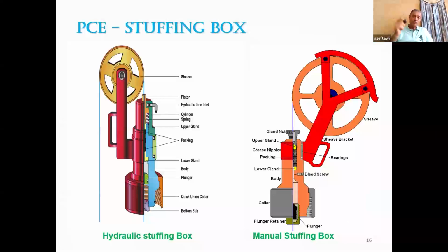The plunger is a closable barrier, because what is the definition of a closable barrier? Close when required. So it's open by default. When will it close? When you need it. And now you need it, because it will prevent the well pressure from going out. So the stuffing box is always your primary barrier, even if there is no wire. It is a closed barrier, but inside it there is a closable barrier.